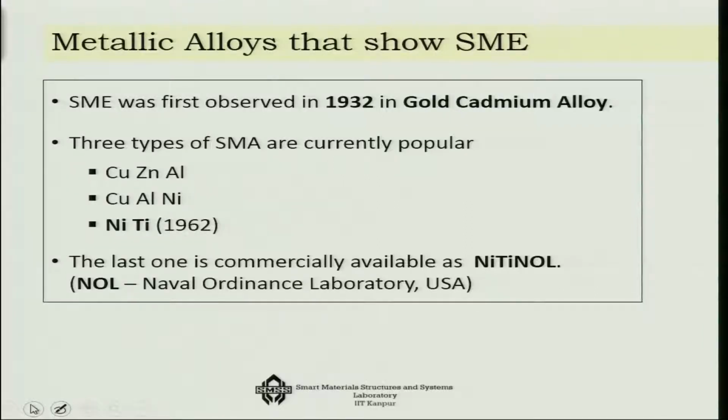There are three types of SMA that are currently popular. One is copper zinc aluminum, another is copper aluminum nickel, and the other one is nickel titanium alloy. So, it is a binary alloy in comparison to the other two, and since 1962 when this was discovered, it is becoming more and more popular.